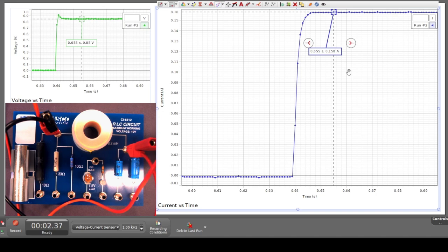Now, technically the wires I'm using will have resistance as well. Normally we talked about how we can just ignore the resistance of wires. Well, in this case, the only thing hooked up is wires. I mean, the inductor is just a wire, and the wires I'm using to drive this and connect everything have their own resistance. So all of this is going to add together. They're all in series, so we're just going to treat it as one resistance, and we'll blame it all on the inductor for now, and we'll see how accurate that is.